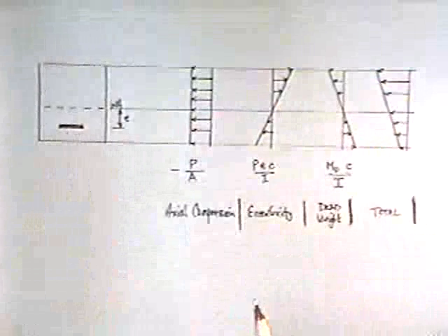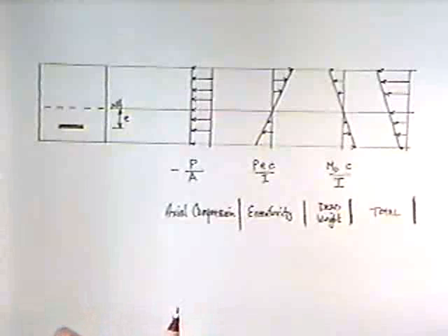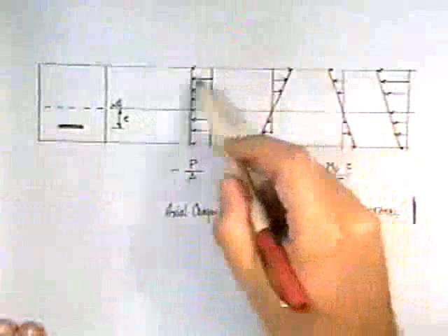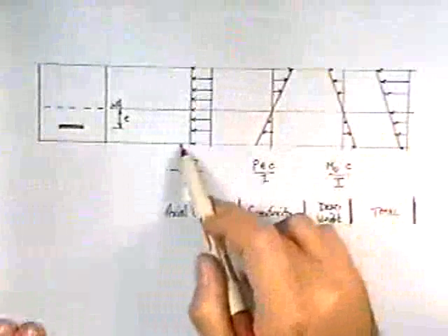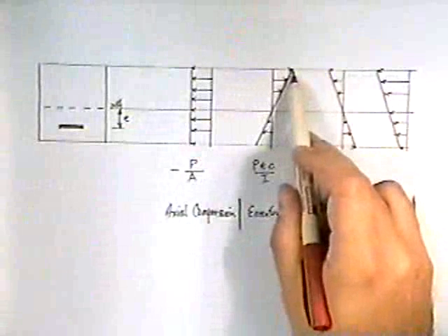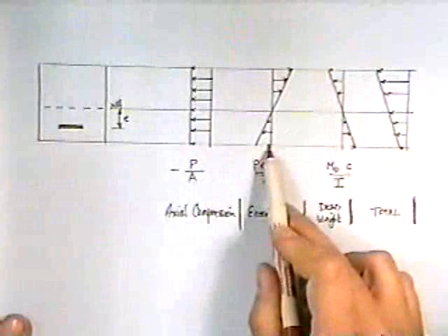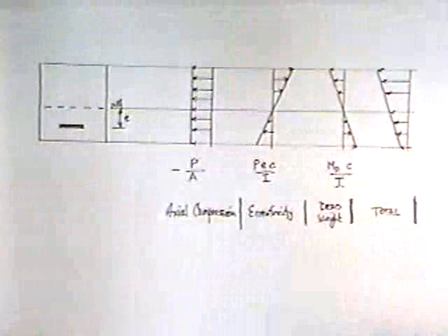If I take this beam and I post tension the bottom, what side of the beam is going to go into tension, the top or the bottom? If the tendons are on the bottom, they're trying to pull in, so the top part is going to try and push up, right? So you see here, if I draw compression stresses going to the left, all my compression stresses go to the left. You see at the top, the tension stresses go to the right. So the top part goes into tension here, the bottom part goes into more compression.